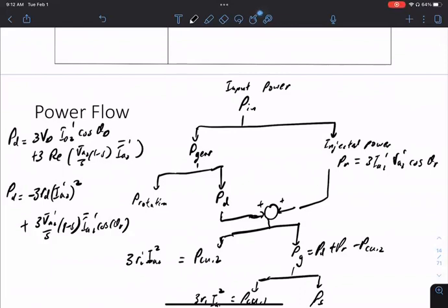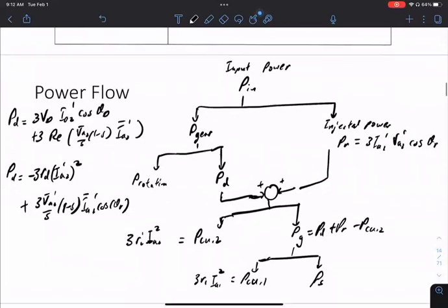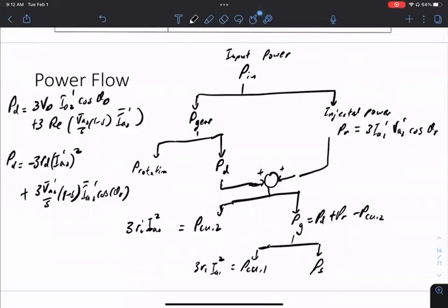Before going to the next step, one thing I'll say is that this also gives you some of the complexity in these equations. A lot of questions we ask in your homework and in the exam go in this direction: given our numbers, compute all the power flows and see what the power flow is. In practice, you don't do it this way. In practice, you do it the other way. I want some power coming out of the stator. S changes when speed changes. Now go backwards, compute all these things.